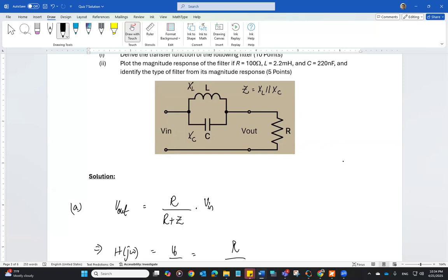So we know that it is either a band stop filter or a band pass filter. Actually, it's not a band pass filter, because you have the output at low frequencies and you have the output at high frequencies. That means it has to be a band stop filter. At certain frequencies, your L and C are just going to become an open circuit when they start exchanging energy between them.